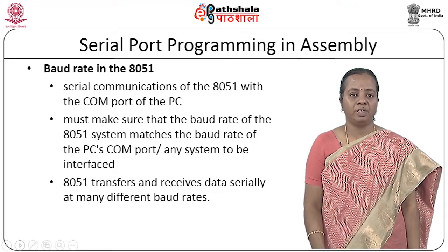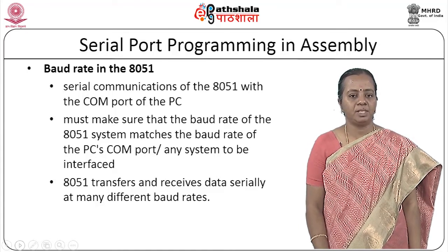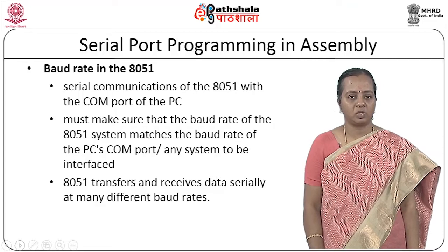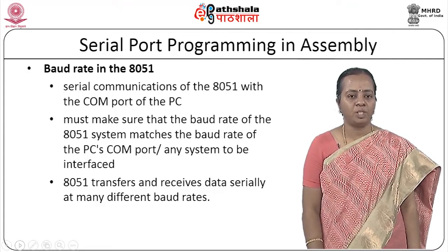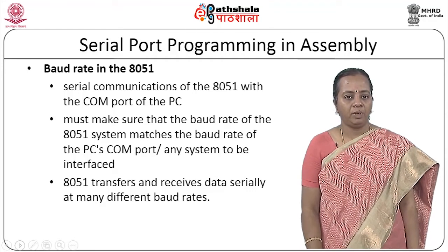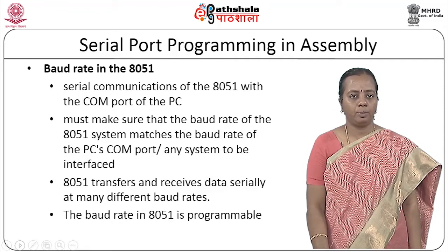We need to configure this baud rate, and it is very important. If I am connecting the 8051 with the PC's COM port or any system, there should be a match between these two. The 8051 can be configured to different baud rates.